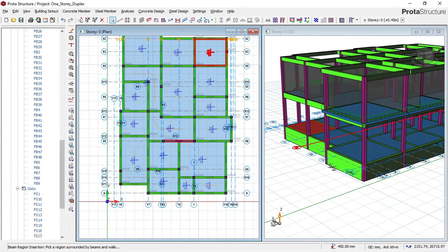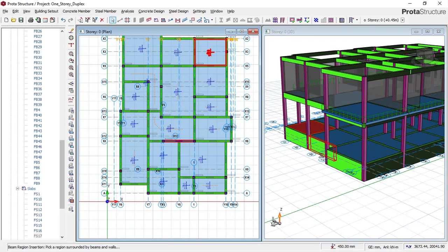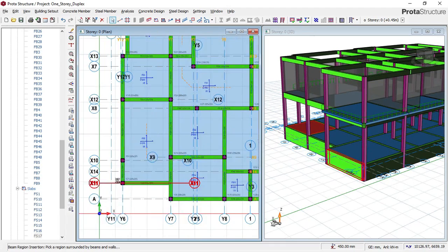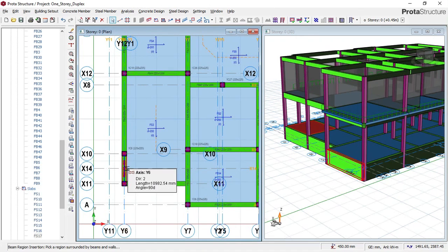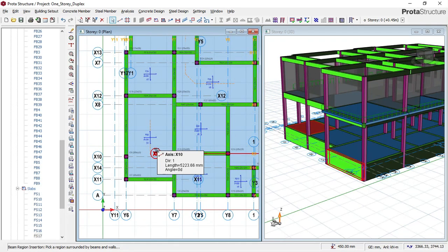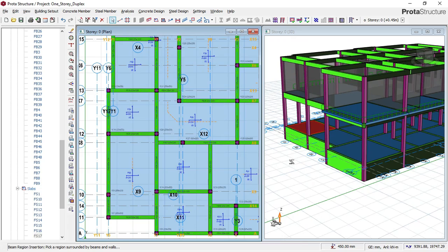So always provide a toe on your raft beam if you're using a raft on beam foundation. You always provide a toe which will take care of active pressure, or what they call overburden pressure, around your ground beams for the raft beams. So right now I'm going to provide a cantilever slab which will act like a toe, and then in part 2 of this video I'll show you the structural detailing of how that works and how you can detail that area, because this software will not be able to detail that perfectly.